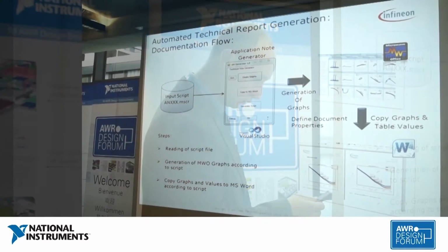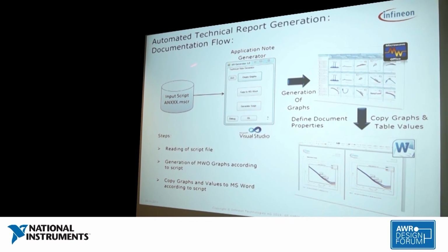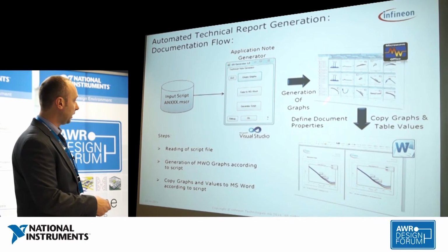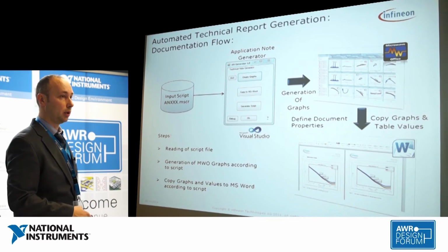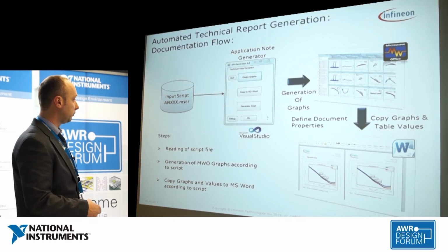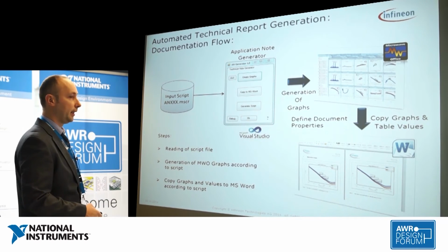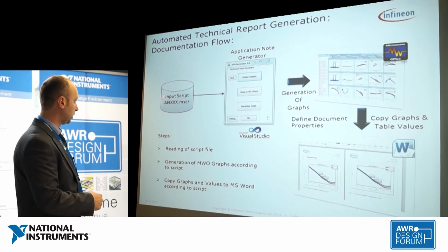So this is a text script, right? It will drive Microwave Office and generate a lot of graphs, which then will be automatically put into the Microsoft Word document. With such a solution, we can reduce our documentation generation time from 2 weeks to just maybe half a day, including the creation of a script.